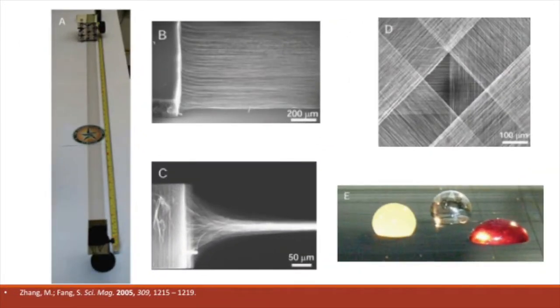In 2005, Mei Zhang and a group of scientists at Nanotech decided to take a different approach to growing carbon nanotubes. Instead of aiming for longer lengths, they managed to synthesize a multi-walled carbon nanotube sheet that was 1 meter long and 5 centimeters wide. The carbon nanotubes were grown in vertical forests by catalytic chemical vapor deposition, where their lengths were generally kept within 70 to 300 micrometers.